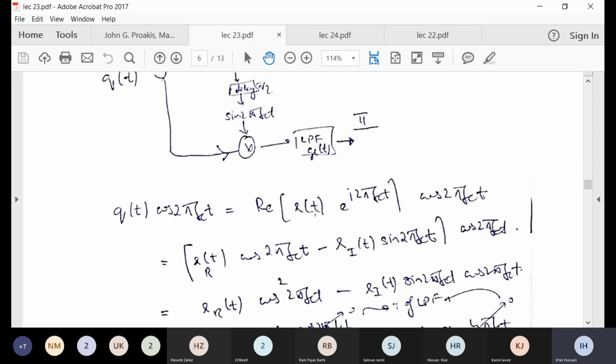R(t) can be written as R_R plus jR_I, its equivalent, you know, this is baseband signal. So I know my baseband signal, it could be real, I know, but in general it could be complex. Okay, and it could be complex because of any reasons, because the sequence was complex, acceptable, because the channel was complex, whatever the reason, that has to be covered.